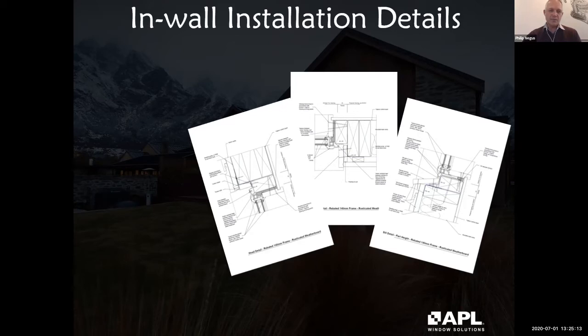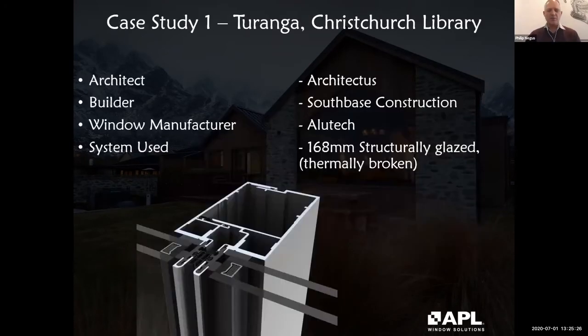And so in this particular case, you're relying on a set of head jam and sill flashings to actually keep it weatherproof. But it's actually getting the water out that is the problem. It does actually make the installation more expensive as well, and adds complexity to the installation. So it's not for everyone, but for people who want thermal performance, they would probably prefer to use that as opposed to mounting it over a vented cavity.